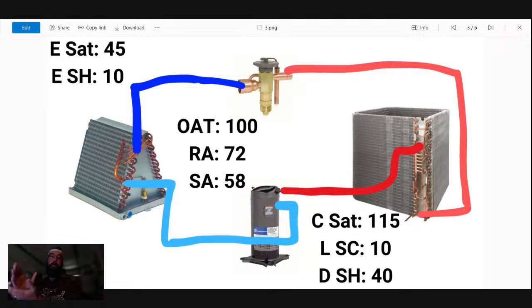So you end up dropping from medium speed to low speed. That gets our evap saturation down between 38 and 40. Superheat still maintains at 10, being a TXV, no issue there. The rest of the system still maintains where it's at, no issues there. But our supply air now drops even further, to where we're pushing out around 53, 54 degrees once we stabilize. So at that point, we're pulling out a lot more humidity.